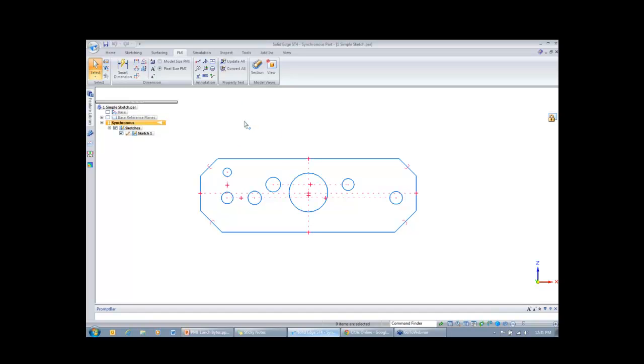Before I go into dimensioning mode, I'll cover some of the small options on the extreme left corner. So small tab here that says overlapping. What it does is, whenever you window select any element, in order to select that entire element, you have to make sure that your selection criteria include the entire element. Okay. So if you don't want that, you can start this command here. What it does is, even if it only touches that element, it automatically gets selected.